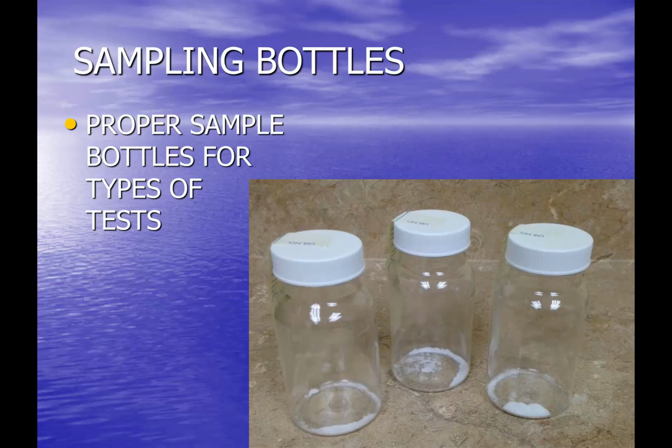We'll talk later on about the need to dechlorinate any water that we are discharging from our system. While chlorine has made our drinking water safe, it's not so good for aquatic life, especially chloramines. So the requirement of the regional water quality control boards is typically that we don't discharge any chlorine to the receiving water. So if we're going to be discharging anything, we'll use sodium thiosulfate once again to neutralize the chlorine before it goes anywhere.